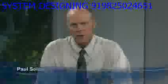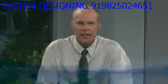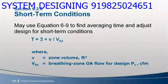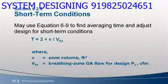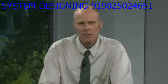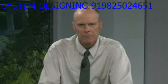Paul? For any zone with a fluctuating number of occupants, design calculations can be based on average zone population rather than peak zone population. Average population is calculated over a defined time period. The equation for calculating the averaging time period is based on the volume of the zone and the breathing zone outdoor airflow that would be required for peak population. Averaging zone population results in lower breathing zone outdoor airflow, lower outdoor air intake flow, and potentially smaller capacity equipment.